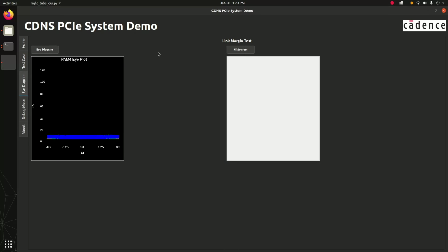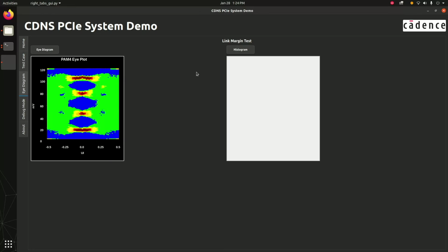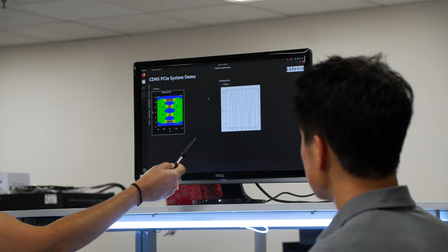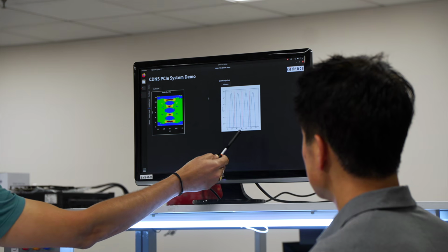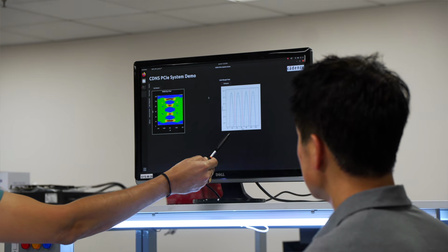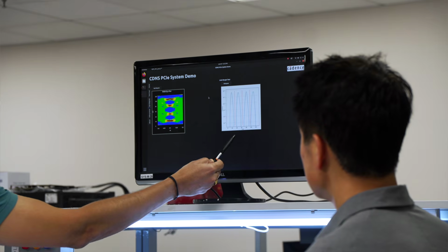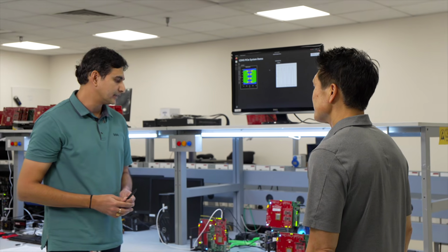On the left, we see a non-destructive eye plot, which clearly shows a good linear eye. On the right, we see the histogram of the data at the output of the DSP, which clearly shows 4 different PAM4 levels with good margin between them. This is one of the tools that we use to evaluate the margin on the receiver, which is the critical parameter in ensuring the link's robustness.